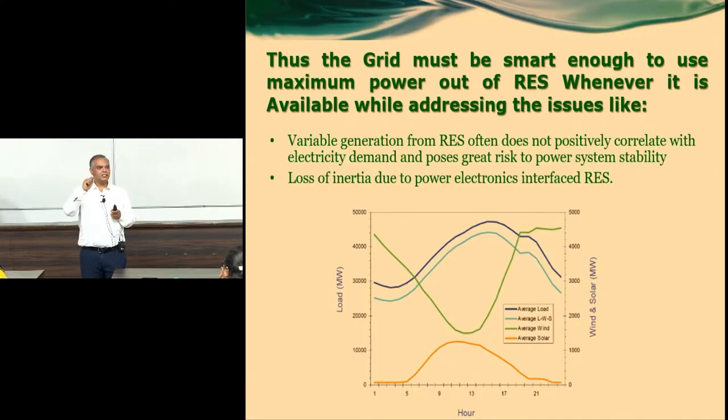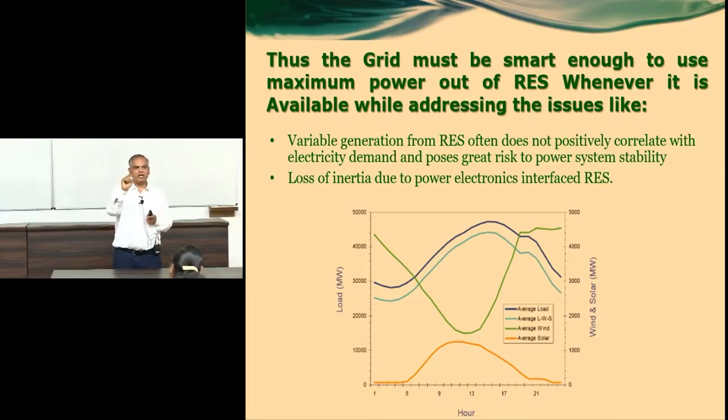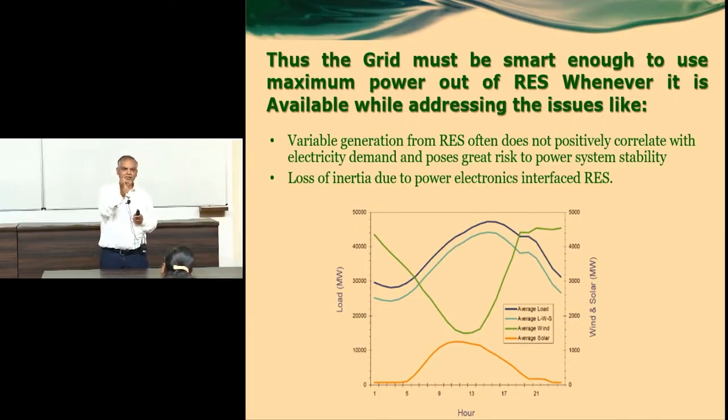That is the energy. If the initial operating speed is omega 1 and the speed has been reduced to omega 2, then the energy is half J (omega 1 square minus omega 2 square). That amount of energy is already available inside the rotating mass in the form of inertia. J is the inertia constant.